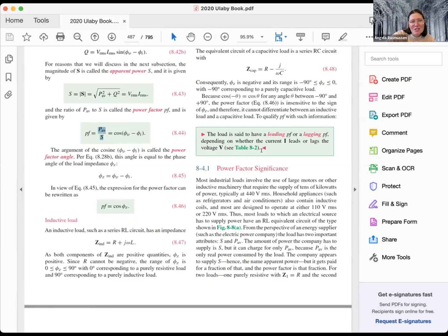I don't know, did that answer your question fully? Just to clarify, you're saying the closer it is to 1, the fewer components that are capacitors and inductors. Correct. So less of an imaginary portion to it. And if it is equal to 1, it will be all real elements. So there are no time dependent elements typically in there, or the time dependencies cancel out, so you don't have any contribution from them. So they're just all passive. Yeah, they would just be resistive, with a power factor of 1.